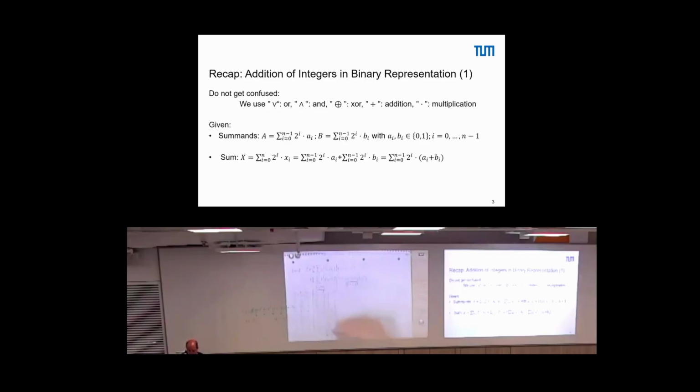We can interpret this as Si equals Ai XOR Bi XOR Ci minus 1. Yeah? So if 1 of the bits is set, then we have 1, 0, 0, or 0, 1, 0, or 0, 0, 1. Yeah? Which gives, with an XOR in between, a 1. If we have 2 bits set, these two, or these two, or these two, then an XOR of 2 1s always results in a 0, so this gives a 0. If we have 3 1s, this results in a 1. Right? Okay?